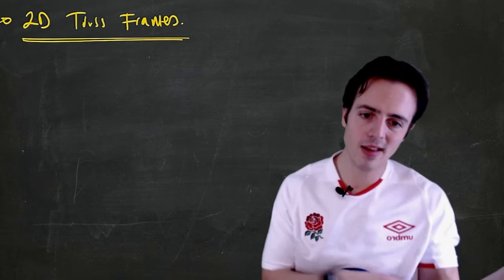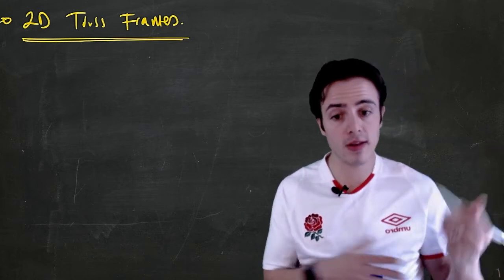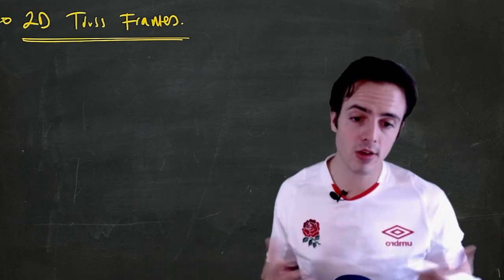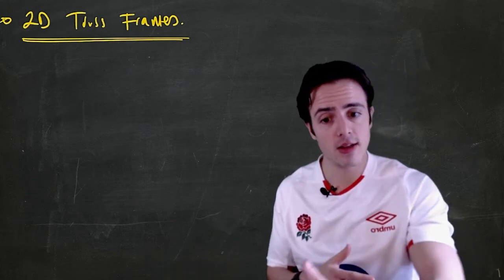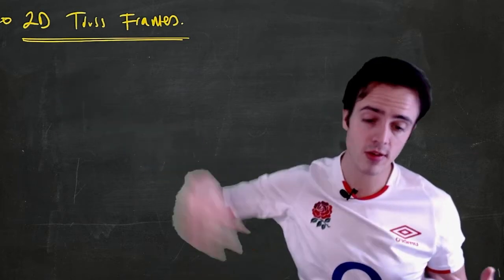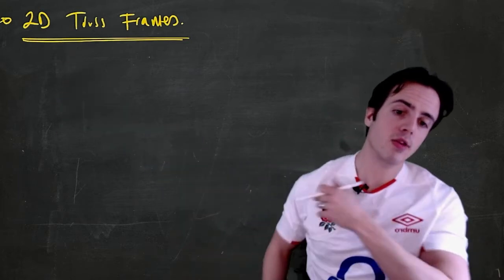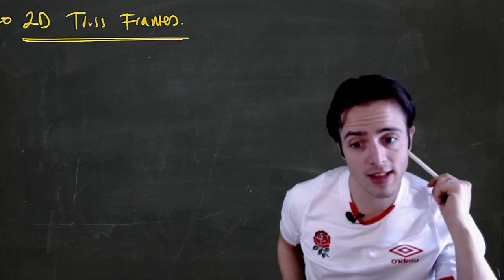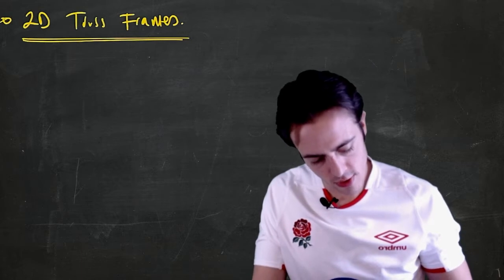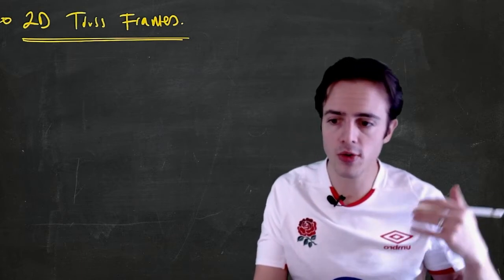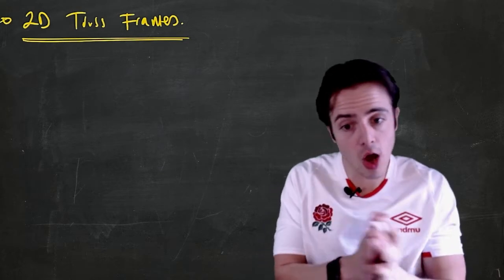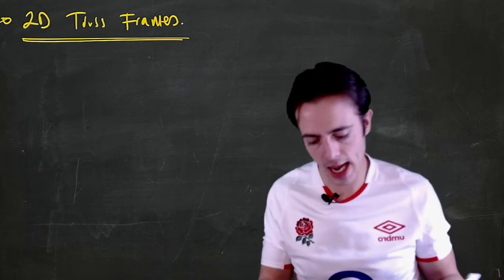Okay, we're looking at two-dimensional structures because they help us understand higher order problems. We've already shown that through looking at shear center, that helps us understand the concept of elastic axis, which is a 3D problem, by looking at 2D structures. We're going to look at 2D truss frames because they help us understand or utilize these methods. So truss frames are composed of two force members, and those force members are capable of only taking forces along their principal axis.